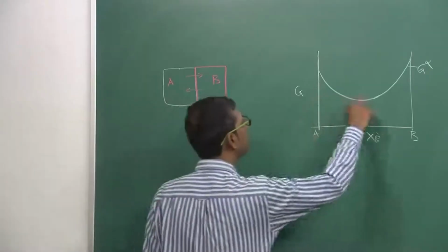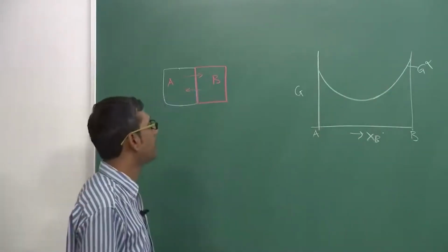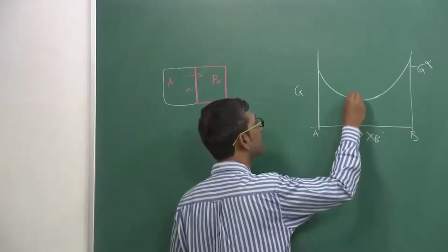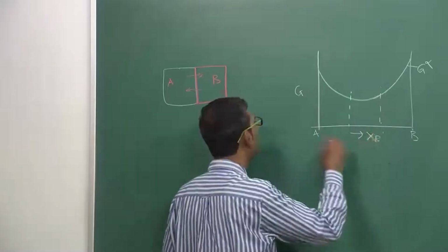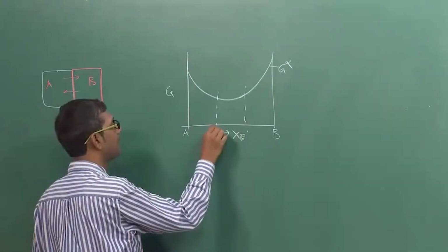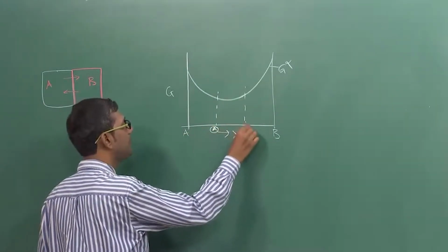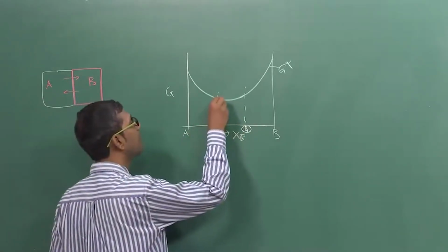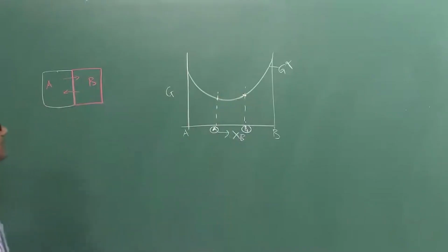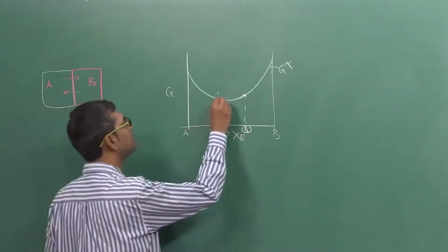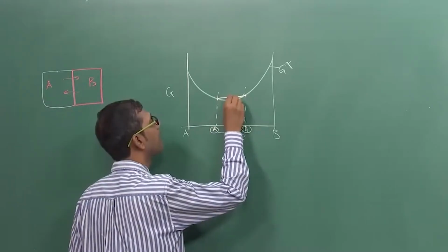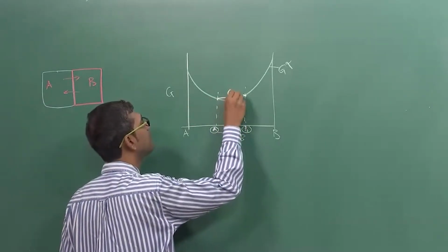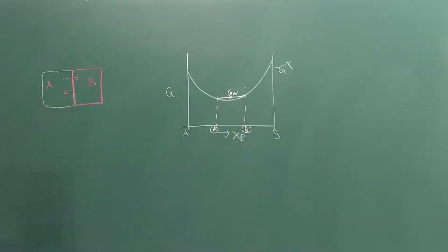So, therefore, the free energy composition curve will be only one. Now, if I mark the compositions here, let me just mark by white line, composition here, composition there for A and B. Suppose this is the A metal composition and this is the B piece composition. Okay. Now, obviously, the free energies of these solutions are marked by these 2 points. Now, it is very clear the average free energy of the system will be somewhere lying there, right, because we have joined them together. This is the average free energy of the system. Am I clear? That is what it looks like.